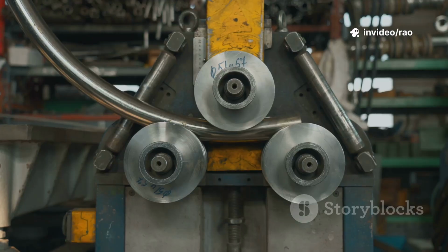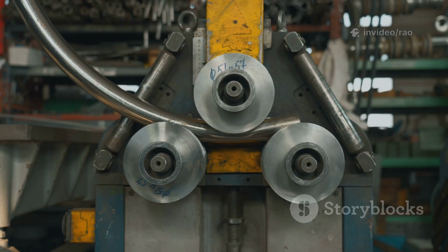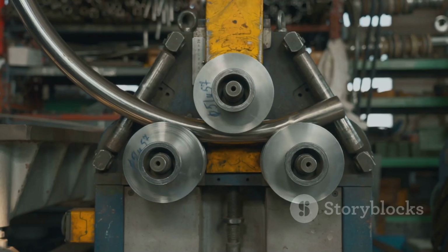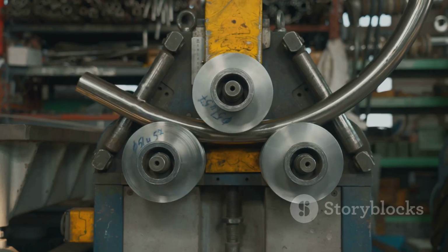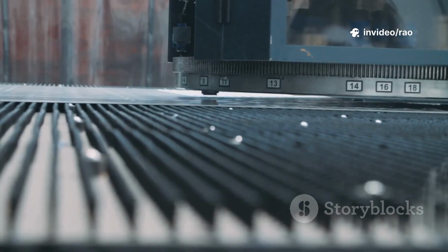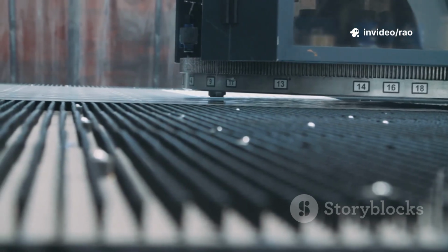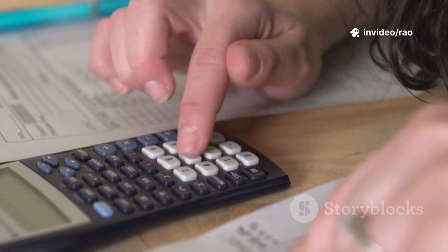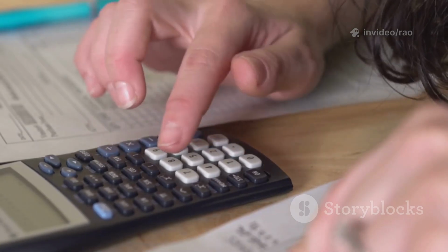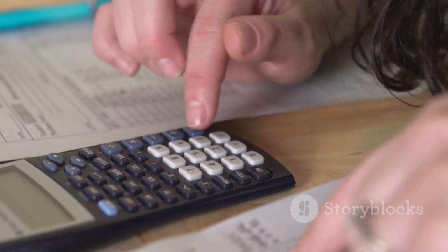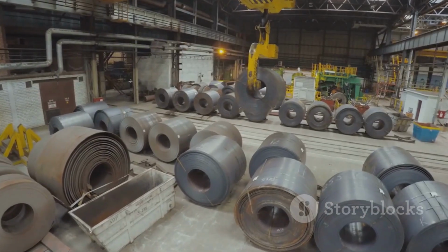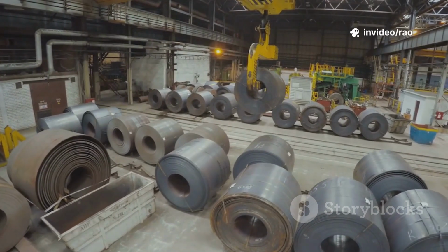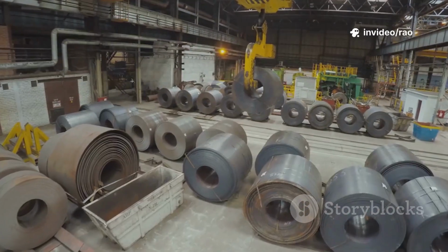Having these precise cutting lengths is essential for the bar bending schedule, which is the document used by steel fabricators to prepare the reinforcement for the site. With the number of bars and the cutting length of each bar determined, we can now proceed to the final and most important part of the estimation, calculating the total weight of the steel. Steel for construction is ordered and paid for by weight, in kilograms or tons, not by length.